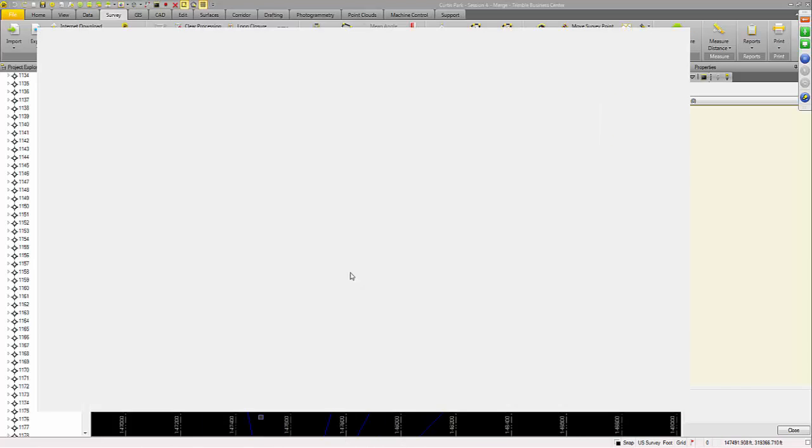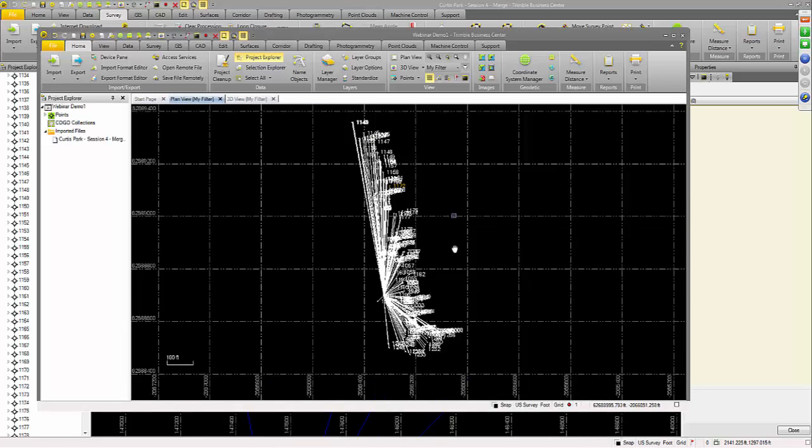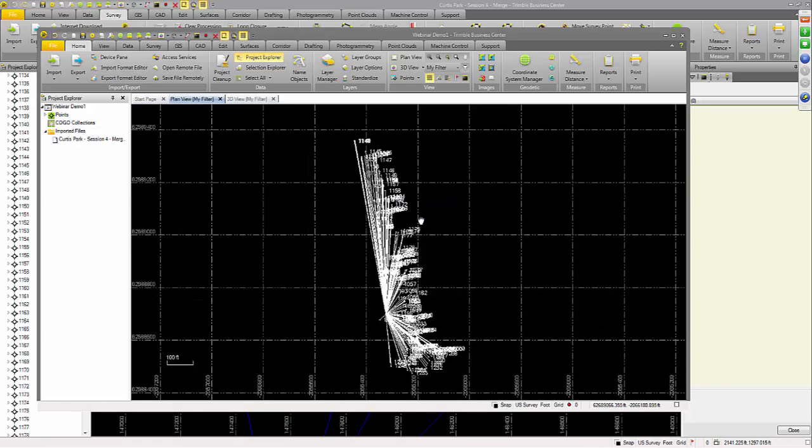One note on that is KMLs are natively, and most effectively, in a global coordinate format. So the KML that you create inside of Google Earth will automatically be stored in that, so you won't have any issues. One thing I did notice was if I mixed and matched coordinate systems between TBC projects when I was exporting and importing, I could get my data flipped.